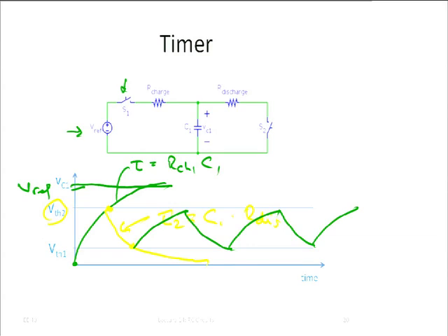Yes? Okay, so if you already looked at lab 4, then there are 3 resistors, 1, 2, 3, and they set up V threshold 1 and 2, which are 1/3 and 2/3 of VDD in that particular case. But of course, you can choose any kind of values, and here I just didn't get into that kind of detail. I thought I'll leave that for you in the lab, so there you have another go at it. Okay, so here we just make these two voltages. You could set them up with a voltage divider or with the lab power supply, whatever you like, right?